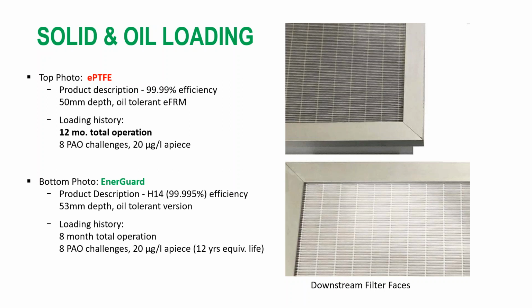But premature loading is definitely seen. In this experiment, done in a life science facility, they actually did challenge with PAO. Not a lot. The concentration is at the recommended level of 20 micrograms per liter, which is quite low, on par with what you should be testing at. And again, it did not last a full year in operation. That's not unusual, based on studies that I've seen in other parts of the world.